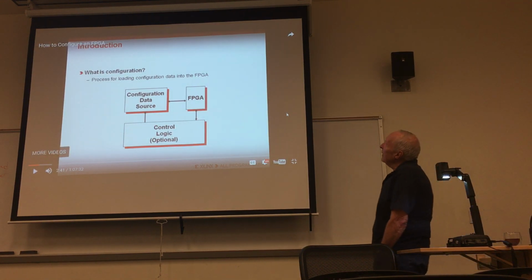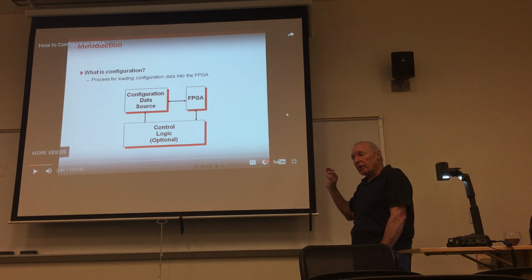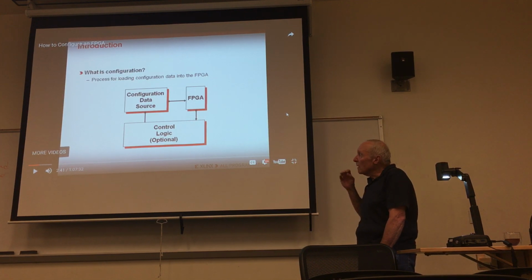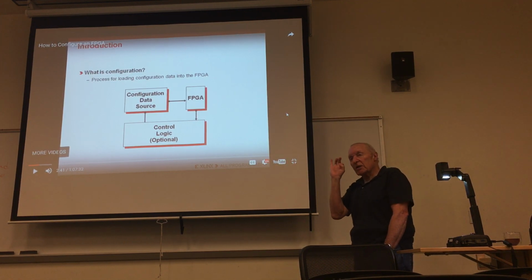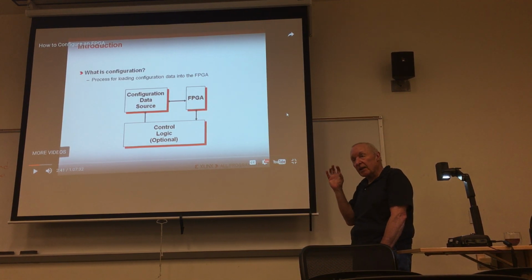Yeah, no doubt. The FPGAs are SRAM based. They could be, in principle, made non-volatile, so you only have to program them once. But those memory cells are larger than static RAM cells, and the objective here is to get as much stuff into the package as possible, so they're SRAM based.